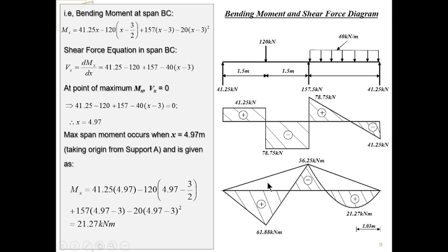So if we bring that to superimpose here, in this case it is inverted. So we will have at the mid-span here, the moment at this point should be what? 90. But that 90 is not starting from origin. 90 is starting from here. So how do we know the value at this point?